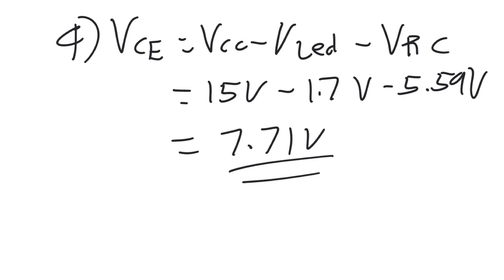Okay, and so anyway, that's it. There's enough current there to light the LED. Somewhere you want 5 to 10 milliamps, rule of thumb, for an LED to get reasonable brightness. Look at the data sheet. Most of them can handle significantly more current. Again, it's application dependent. But anyway, that's number 1.